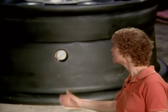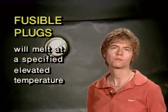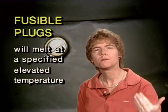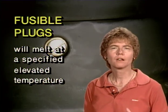Now, on the maintenance of the tires themselves, aircraft wheels often have fusible plugs. For instance, this F-16 wheel has got a fusible plug here. Fusible plugs installed in aircraft wheels, the purpose of them is to be a fuse point to melt at a specific elevated temperature.